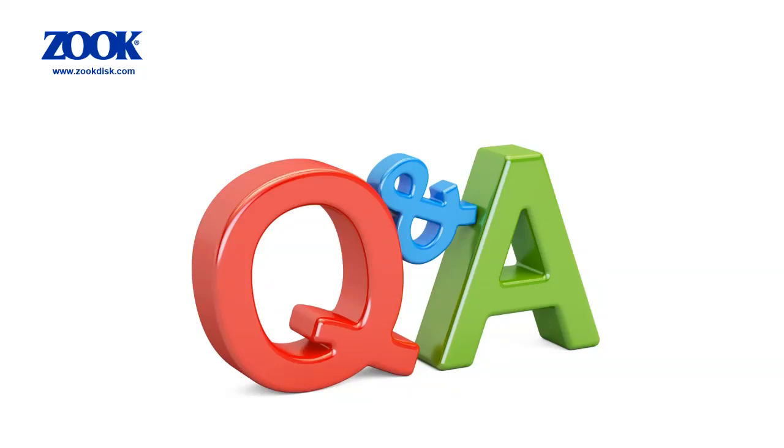Okay, yeah, this is a good question. And in fact, like what you say, a lot of people ask us about this question. Here are a few important considerations about the shelf life. Many rupture discs are shipped in boxes, and it's not uncommon for them to be individually boxed. So the best practice for storage would be to leave them in the box they arrive in. The box provides protection against the environment elements, as well as a certain degree of drop shock protection.